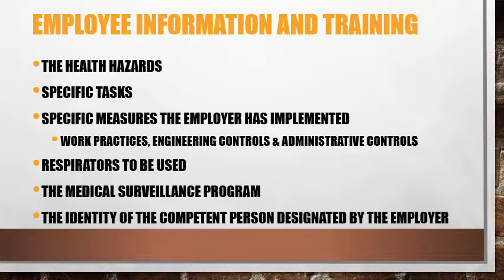Employee training on silica needs to include the health hazards of silica, specific tasks you will perform as an employee that will expose you to silica hazards, specific measures your employer has implemented, such as work practices, engineering controls, and administrative controls to help control your exposure to respirable silica, respirators to be used, medical surveillance program, and the identity of the competent person designated by the employer to help you protect yourself against silica hazards.